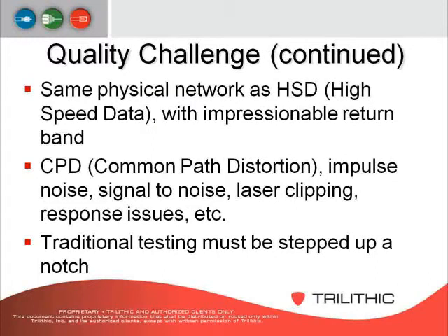There's common path distortions, impulse noise, signal to noise, laser clipping, just particular individual response issues. There are so many things that impact the return that don't affect the forward as much. So you have those challenges.